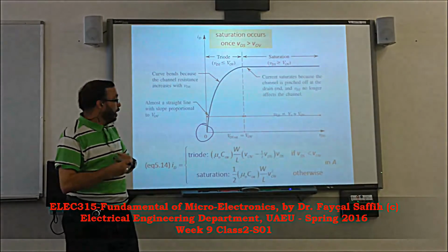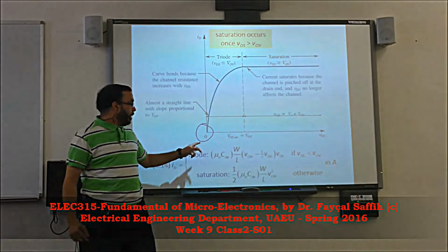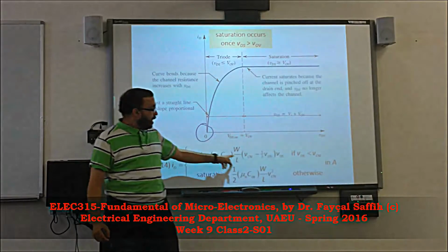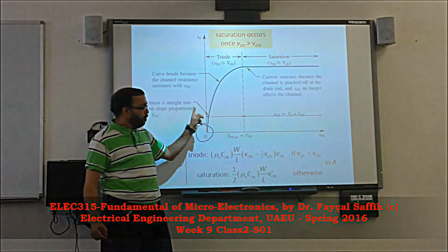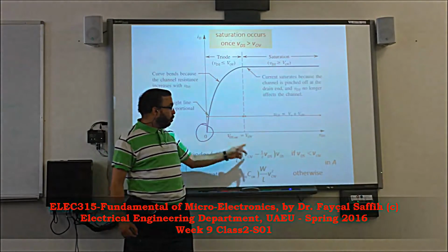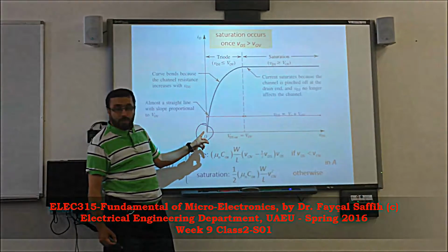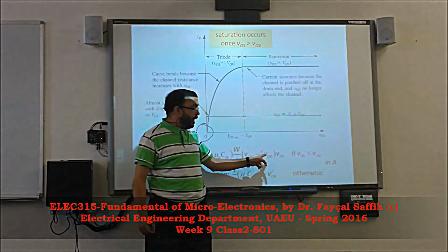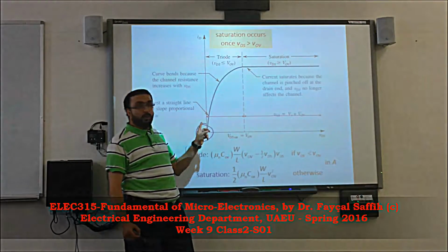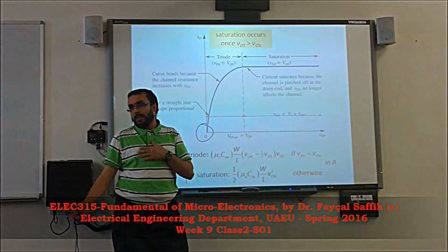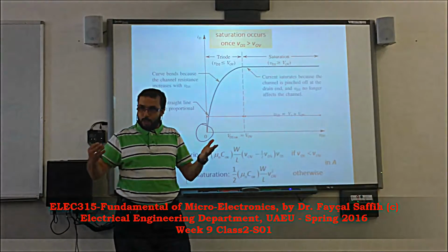Okay, good. So, back to the point that I just mentioned. Here it is quadratic, but in this region it should be linear. How come? To find the same exact equation as before, you say VDS is small, so VDS square close to this region will be neglected because it's small. Something that's small, if it's squared, will be even smaller.